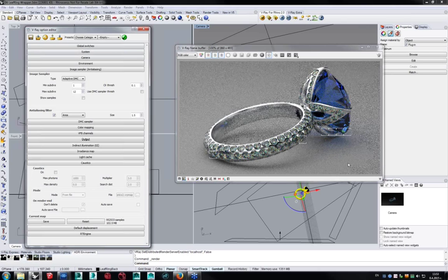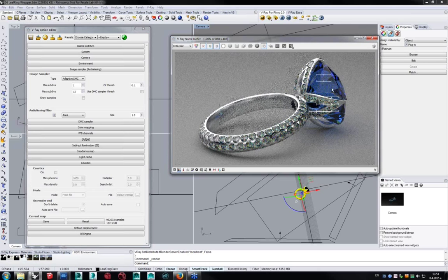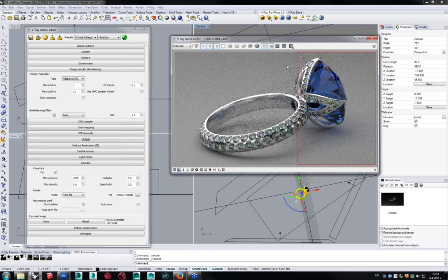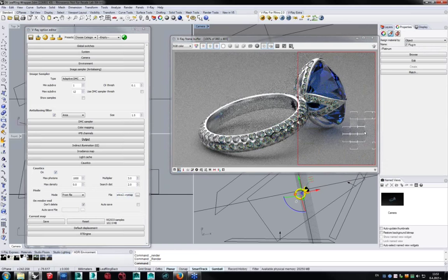these nice light splotches. So one thing that you can do is apply those in post, but you can also create those in a physically accurate manner based on the index of refractions of your geometry, of course, in the shape. So I have set up caustics, and what I will do is just enable these. Let's draw a region over here. Keep in mind you can do that with the production render. Instead of rendering the entire image, you can just render certain regions.